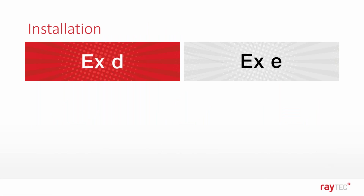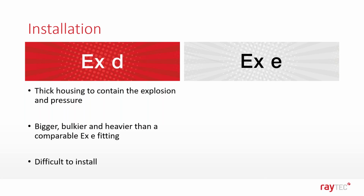Because the EXD luminaire must be capable of containing the explosion and the high levels of pressure which accompanies it, the housing needs to be suitably thick, often twice as thick compared to an EXE luminaire or an EXE product. This means EXD luminaires tend to be much bigger, bulkier, and heavier to install than a comparable EXE luminaire. They may therefore require extra resource during installation, more operators, or the use of specialist equipment.